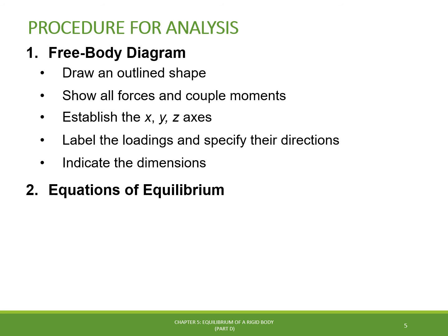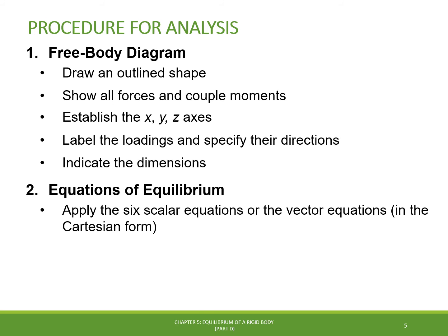Then we are ready to solve the equations of equilibrium, in which we have to apply the 6 scalar equations if the applied forces and moments are well aligned with the axis of the coordinate system and seem easy to determine. Otherwise, we should use the vector equations, preferably in the Cartesian form.